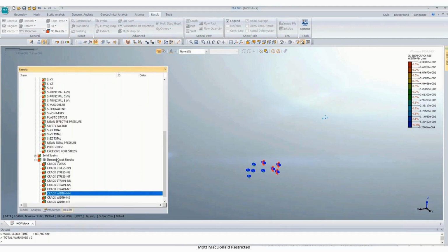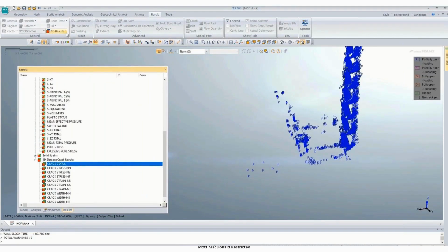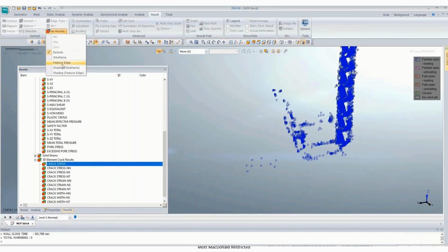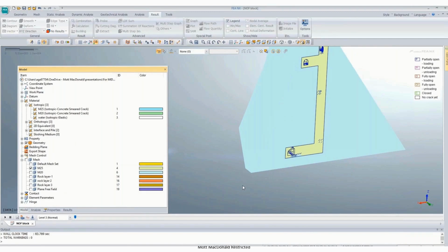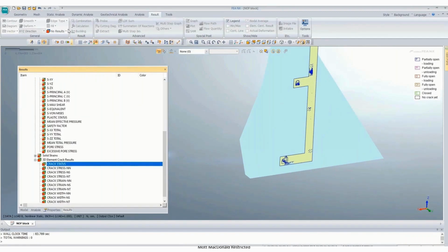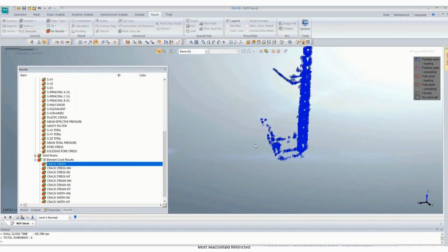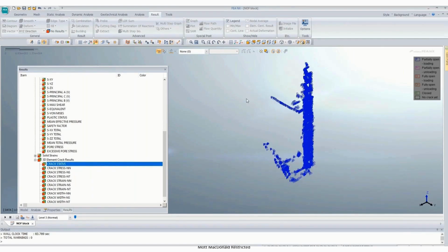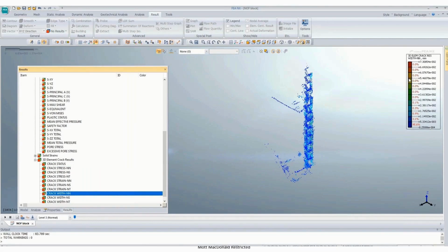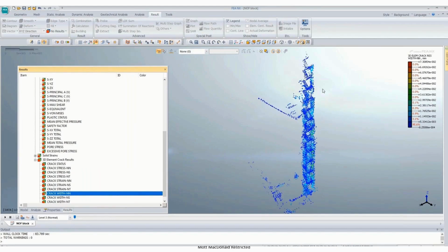Firstly, let's see the status of the crack. Let's consider this wireframe. So M25, let's exclude. Okay, here you can see there are prominent cracks, partially open cracks. These are all flexural members, bending will be there, so cracks will be there. The tension will be more than 0.3 MPa in these cases, but the crack width is still not significant. It is just 0.07 mm anyways. So reinforcement has to be provided here.